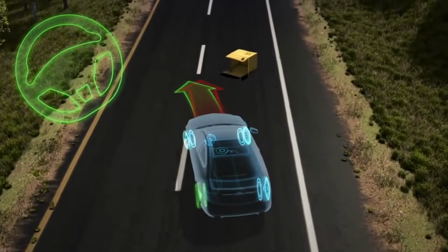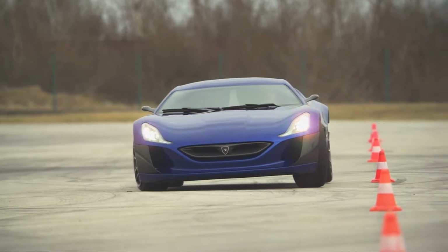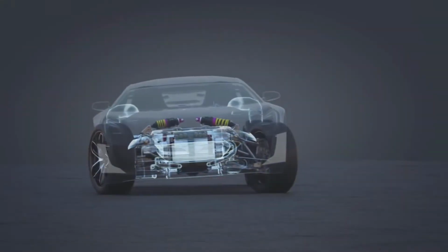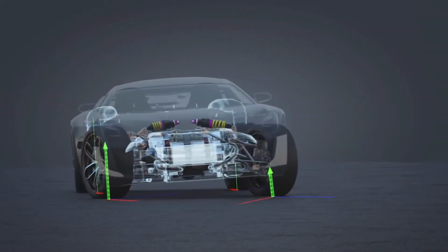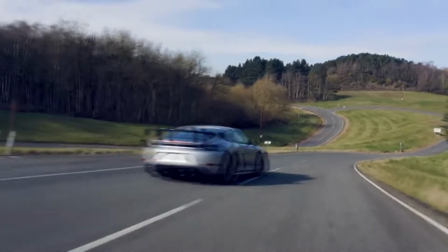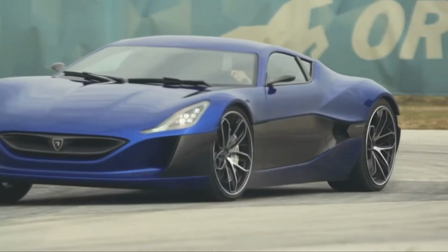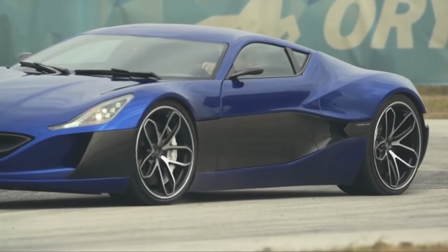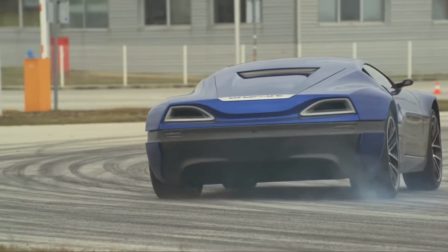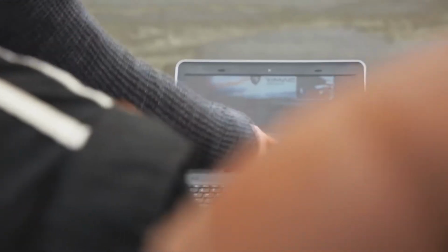Electric cars, on the other hand, have something called torque vectoring. Torque vectoring is when the software in the car calculates how much each tire is gripping the road. If a certain wheel is not gripping the road that well, it accelerates that specific wheel to make it stick to the road. In an ICE car, the engine has to cut the power from going to the wheels and then at a certain point feed the power back in. In electric cars, electric motors are much better at monitoring their power delivery to deal with the conditions. Electric motors don't even have to cut the power. They can just manage the power in a way that makes the car deal with the conditions perfectly.